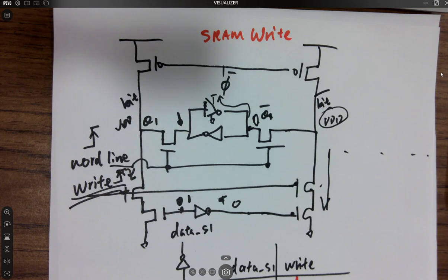So that's important. Another thing is for the SoCs and microcontrollers, you are looking at the memory, like all the buffers we're talking about, right? The buffers are all SRAMs. So in the microcontroller, you store something in a buffer, an array like 20, 24, 32. So these are actually SRAMs being deployed, being used from the C code, right? So you need a certain amount of SRAM.